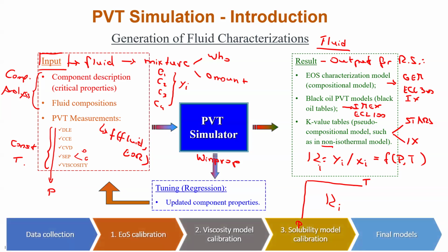And I recommend following those steps. This is very, very standard. It's not created by myself; several authors recommended the same steps. So start with data collection: gather all the data that you have, all the good data. Quality control of the data is very important, especially when you are dealing with oil mixtures. Sometimes the samples can be contaminated by the drilling mud, especially when you drill your well with oil-based muds.